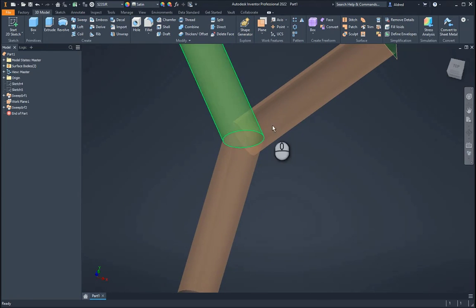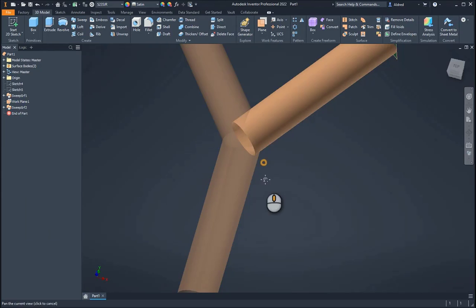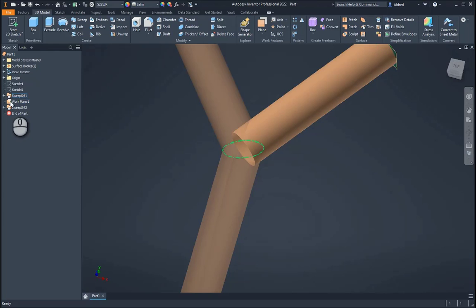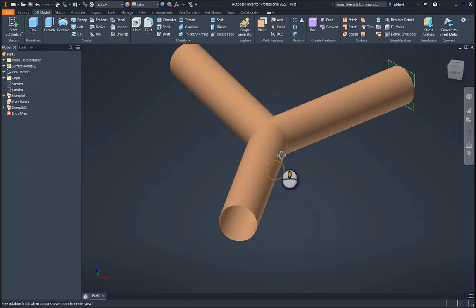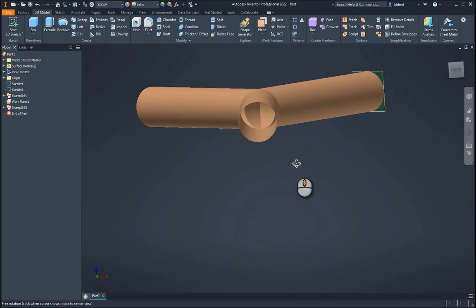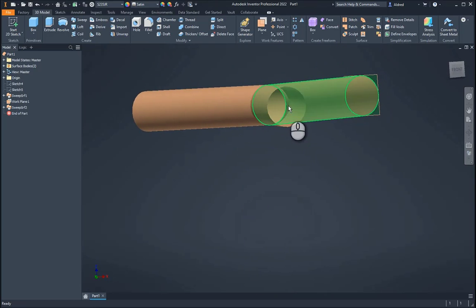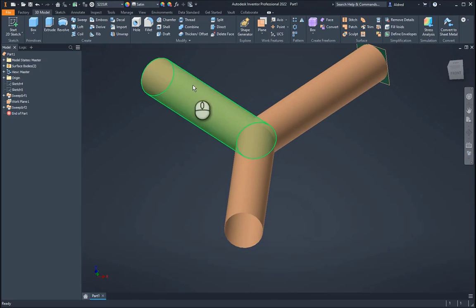Now it's a little bit difficult taking a look at it over here. So if I right click on one of the surfaces, I can take off translucent, or I can put on translucent, take off translucent for both of them, so I can actually see what's going on. That's kind of what I want, but we know that there are surfaces in there that I want to get rid of. If I look at inside, you'll see that I need to cut away those two surfaces over there. So let's go to our surfacing tools.